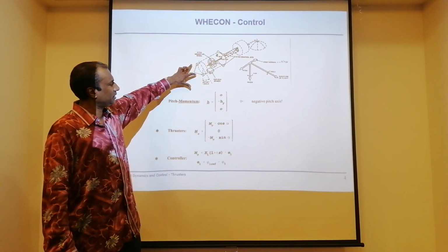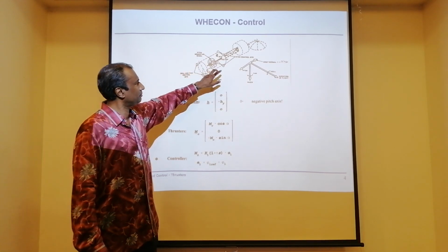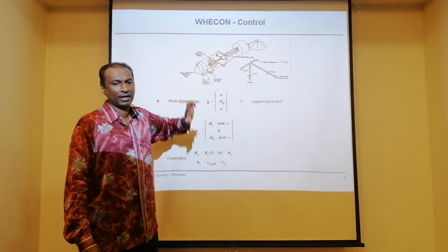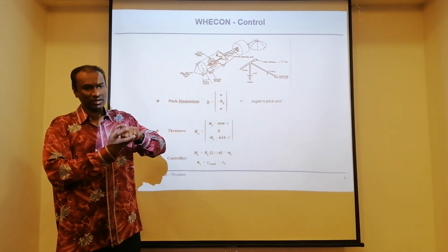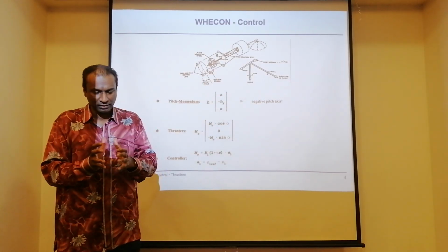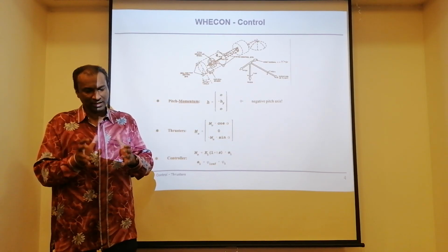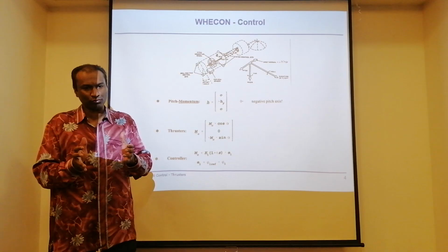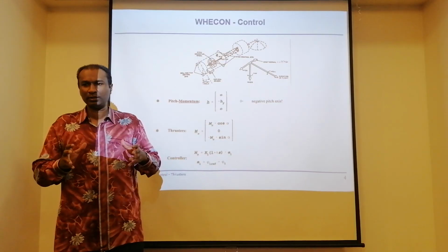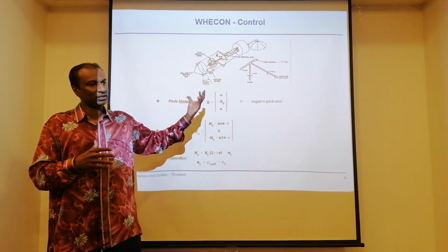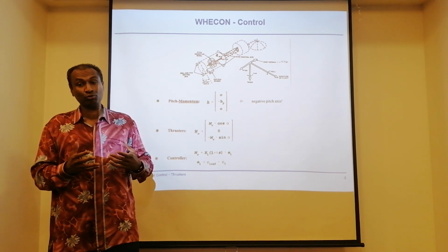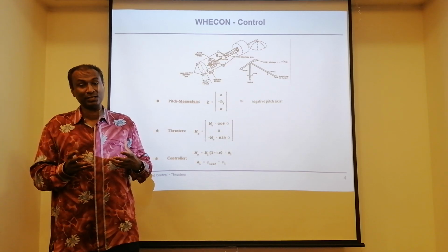You have to zoom in to read this clearly. So you will have these thrusters. Please note there are two thrusters here. These two thrusters are in charge of the actual body pitch. Remember, I told you when you have a momentum wheel and you want to use it for attitude control also, what happens is that the speed builds up. When the speed builds up, you need to dump the wheel. We have learned that. In the last chapter we used magnetotorquers, but you can also use the thrusters to dump the wheel.